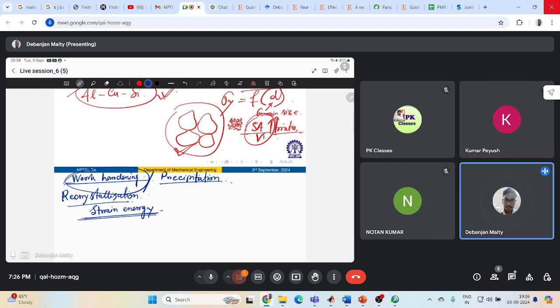So recrystallized grains will always be strain free, right? Those will be soft in nature, just like the grains that have not been deformed. So what is the driving force for recrystallization? The driving force is the stored energy or the strain energy that arises because of the deformation process.